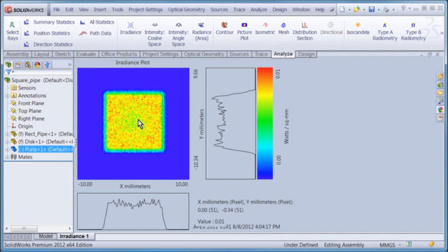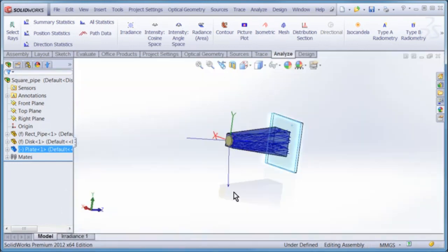It's important when doing light pipe analysis that your light pipe section is long enough to fully homogenize the beam, so your light pipe represents the real physics of your simulation. But similarly, you don't necessarily have to make the light pipe the full length, because a longer light pipe will take longer to ray trace, and once you've reached a certain length, the output isn't going to change.